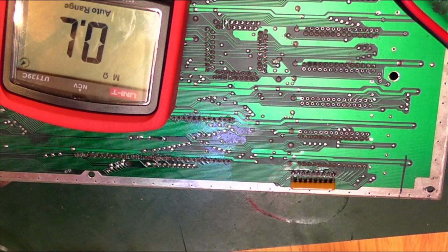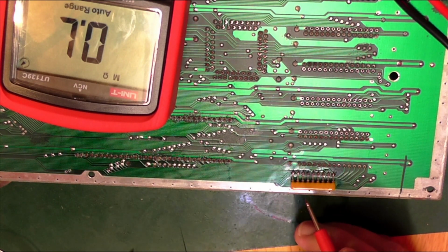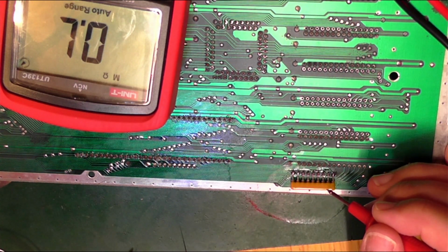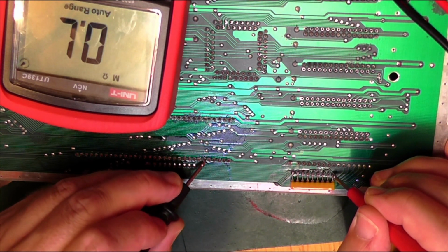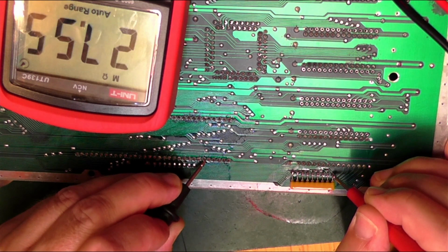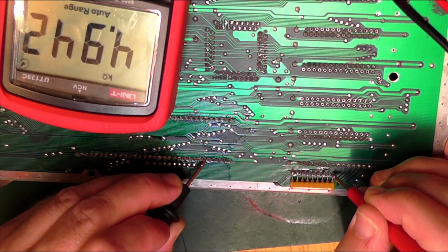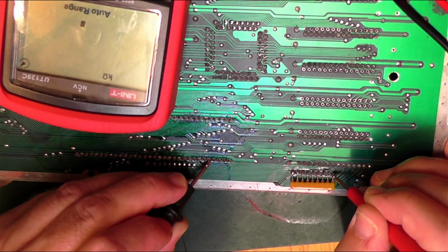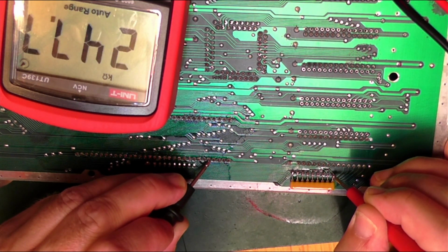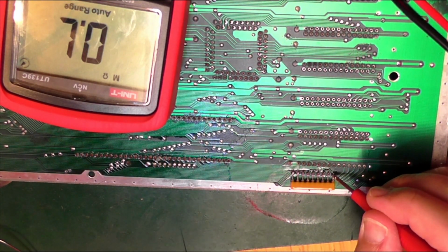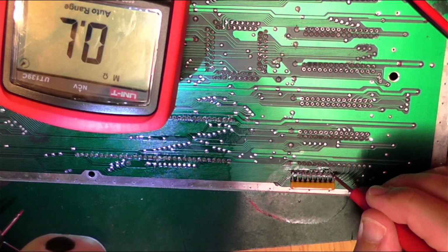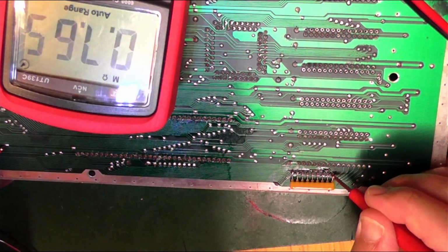That's fine. So let's then quickly check the new resistance between our data line here and VCC. So this one on the end. That's showing 5 kilo-ohms to that line. I can't remember which line it was. Well, first of all, let's just go to the 5 volts line, which is, I think, here.